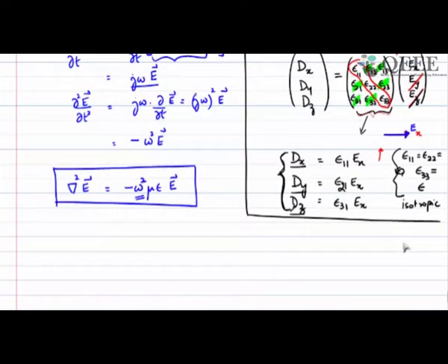Question is, am I losing anything? Actually, I am not losing anything by doing this, because you can ask me this question: are my actual electric fields harmonic? Do I have a single frequency oscillating? And the answer is no, in general it is not harmonic. If I take, for example, an antenna which is radiating electric field, your wireless signals are transmitted at a carrier frequency of 2.5 gigahertz, but on that there is modulation. So it is not a single frequency that is going in, there are multiple frequencies going in.